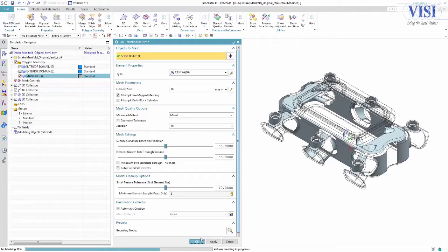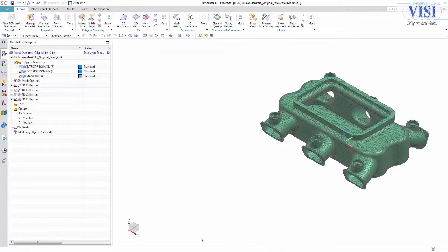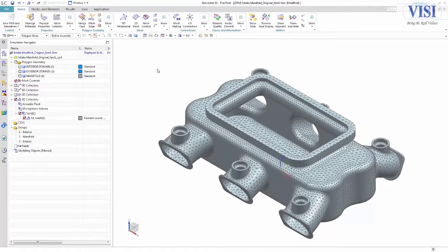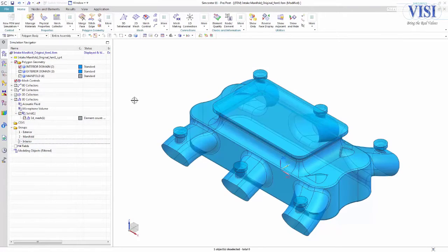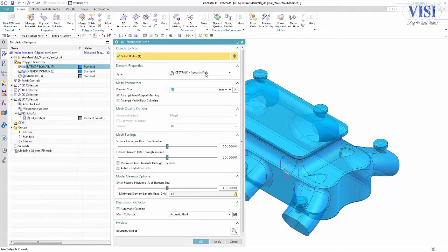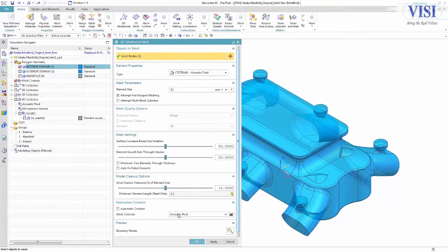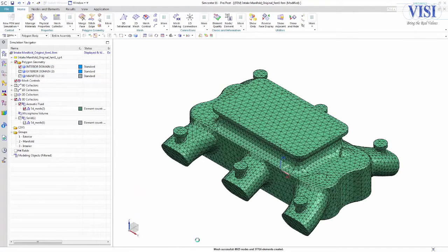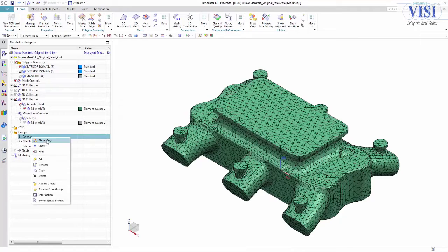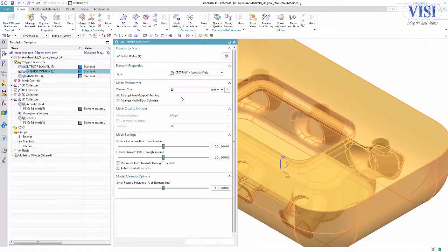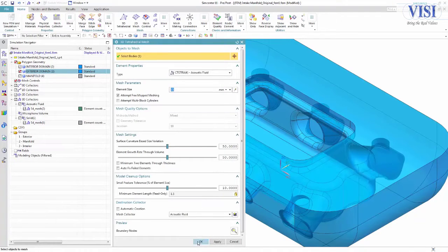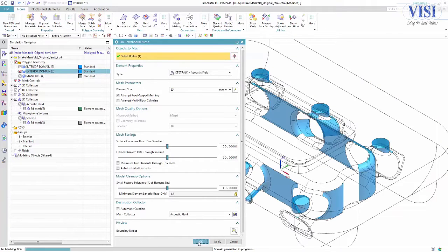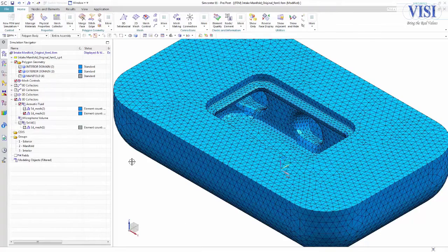Again, a powerful capability with Simcenter 3D is the ability to create multidisciplinary models where you can have a structural mesh and an acoustic mesh generated at the same time. NX Nastran as the acoustic solver can automatically work with otherwise incompatible meshes. Because we have selected a vibroacoustic solution, Simcenter 3D intelligently provides the right element types. For example, note that you can select an acoustic fluid type tetrahedral mesh for the acoustic bodies.